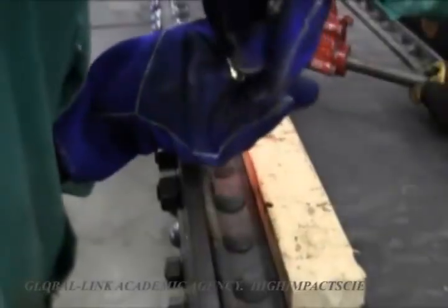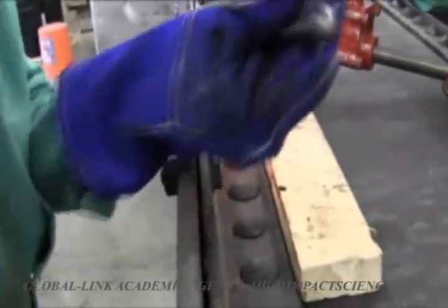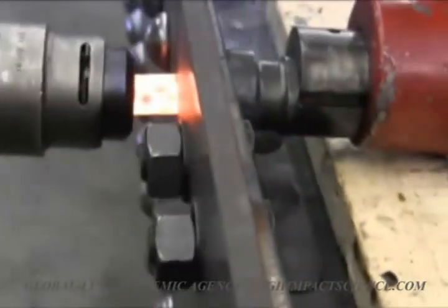Thick metal plates and sheets are joined together by means of rivets. The rivet is fitted when hot and then hammered. On cooling, it contracts, pulling the two plates firmly together.